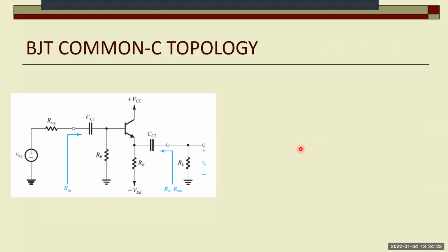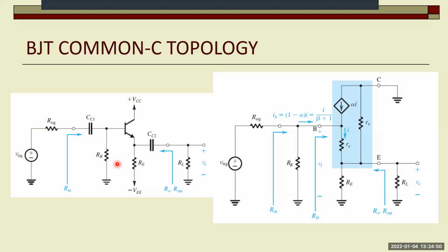Remember it. So, from the base, the output is taken from the emitter. And we have an emitter resistance. Of course, we need to have an emitter resistance and a load resistance. And this is the parallel equivalent of base dividing resistors. So how did we analyze this?